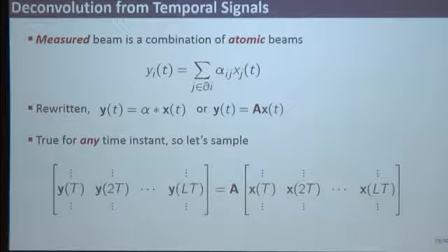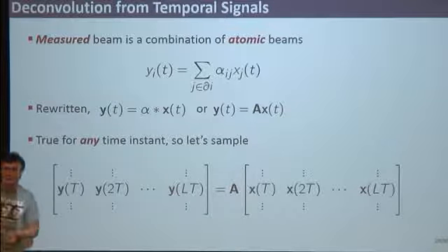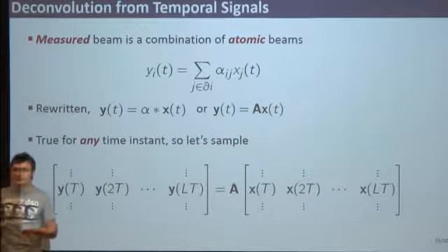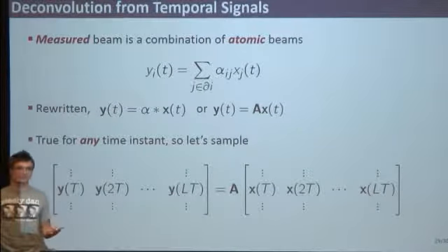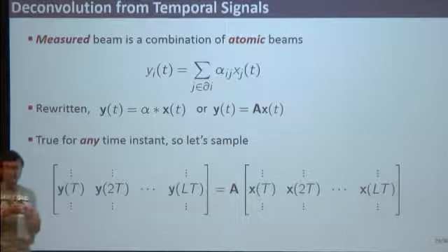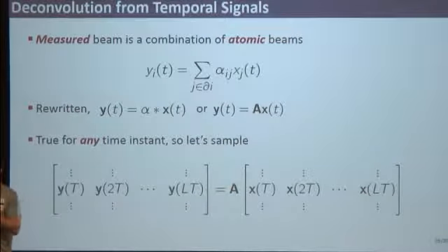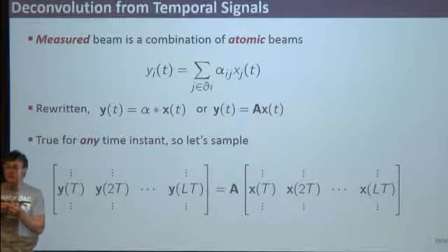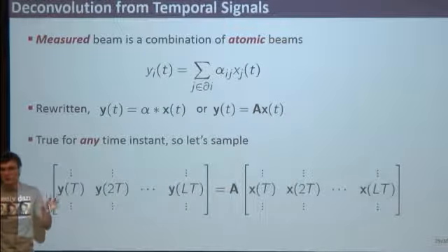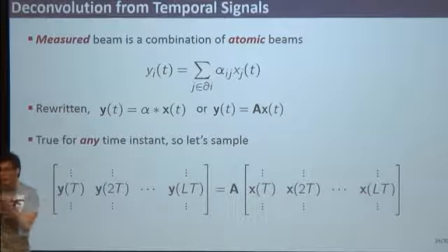But what we don't exploit here quite yet is the fact that this matrix X has horizontal structure, okay? And this horizontal structure is the structure of the pulse. So let me explain this. If you emit a pulse and you have just one reflector in your scene, one point reflecting, what you'll be getting back is the same pulse again, at least in shape. Forget filtering now, but roughly what will come back is the same waveform, attenuated and delayed, right?